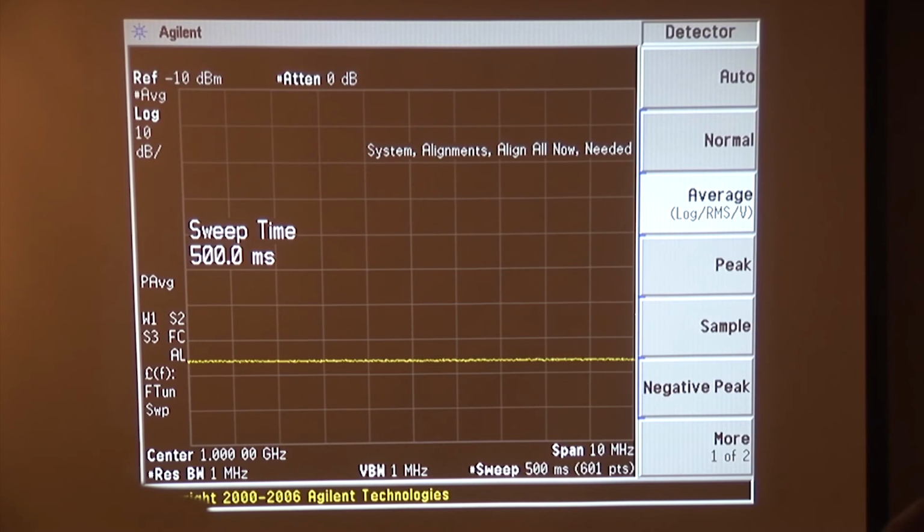You're seeing the noise in the amplifier multiplied by the gain of the amplifier, which lifts this low noise of the amplifier up to a higher level, but the noise level itself is lower than the noise level of the spectrum analyzer. Was that sufficiently confusing? Yeah. You're looking at the low noise of the amplifier multiplied by its gain factor, plus a little bit of additional noise that the amplifier added in.